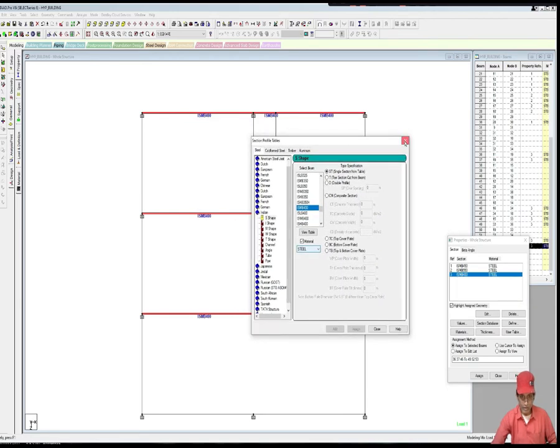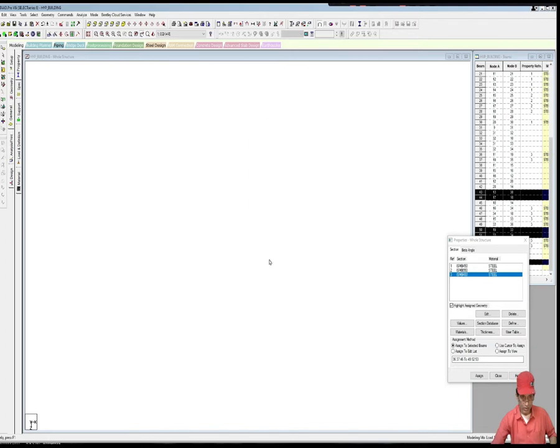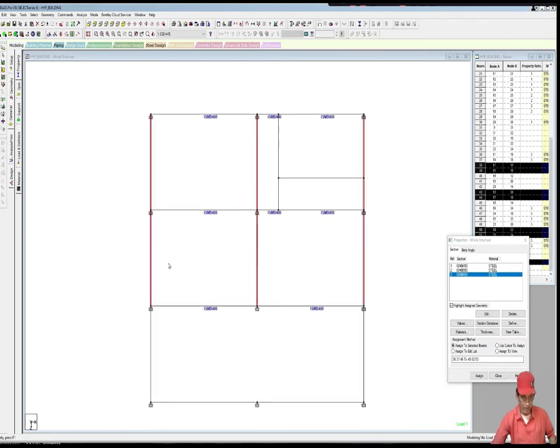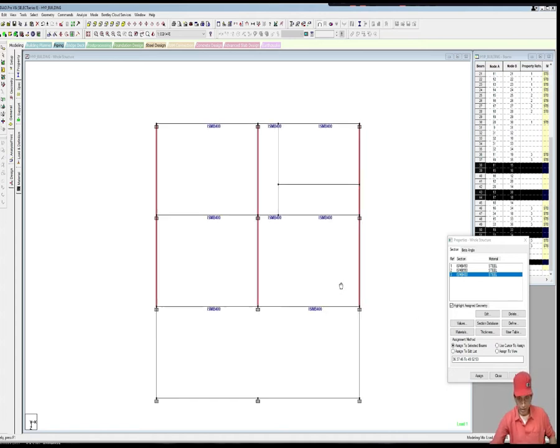Now close this dialog box. Then we have these secondary beams. These are also main beams, but these will be simply supported beam because we have concentric bracing along Z direction. So we can afford to have simply supported beam in these directions. So it will not carry much of the dead load. We'll come to know how it is.